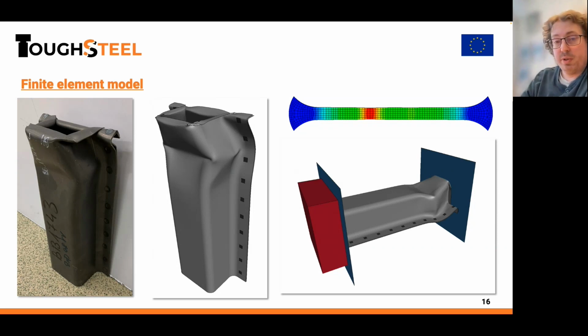And with this internal code, the fracture criteria and hardening can be determined relatively directly using full-field measurements. But damage evolution and softening response often still need to be calibrated using inverse finite element modeling. And this is basically the energy used in the propagation, the post-instability propagation.